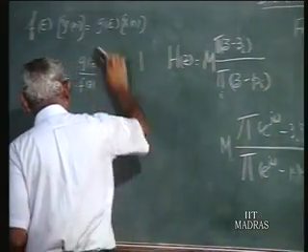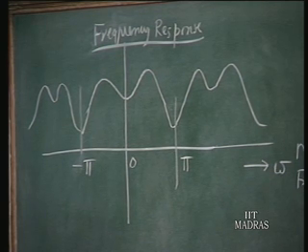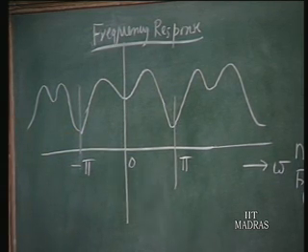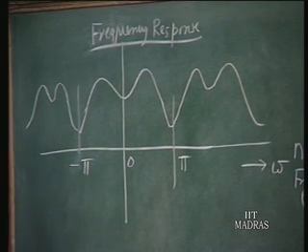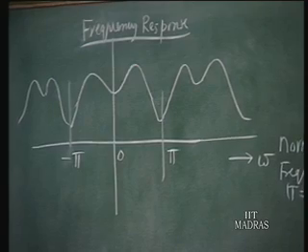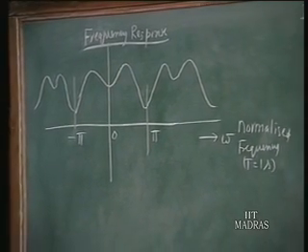a little more in greater detail. So, the frequency response function, suppose you want to plot the magnitude of the frequency response function as a function of omega, then as you can see it must be periodic in character, because as you move around the unit circle you come back to the same values after every rotation through 2 pi radians. So, this is periodic in character, and that is something which is a fact of life as far as discrete time signals and systems are concerned.